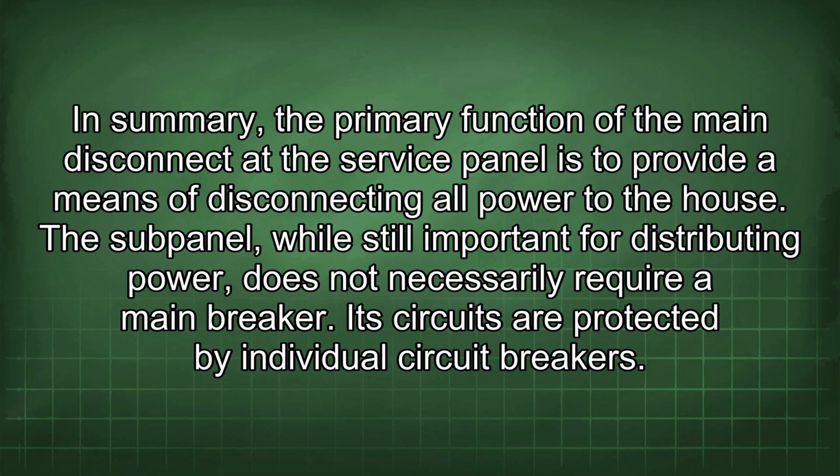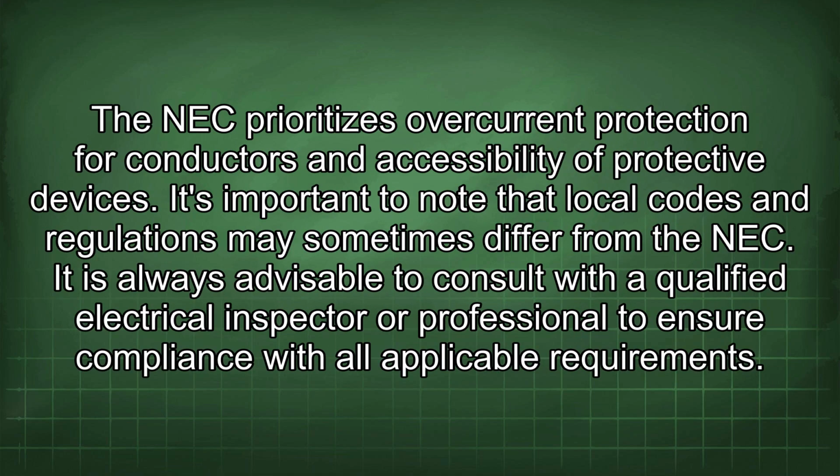The subpanel, while still important for distributing power, does not necessarily require a main breaker. Its circuits are protected by individual circuit breakers. The NEC prioritizes overcurrent protection for conductors and accessibility of protective devices. It's important to note that local codes and regulations may sometimes differ from the NEC. It is always advisable to consult with a qualified electrical inspector or professional to ensure compliance with all applicable requirements.